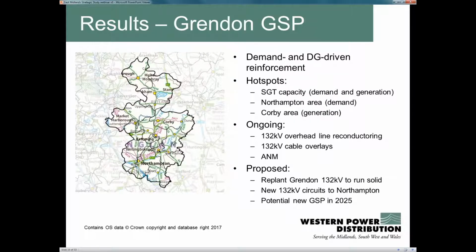Grendon GSP has both demand and generation driven reinforcement requirements. These are primarily against the SGTs for both demand and generation, and then more significantly for Northampton as demand and Corby as generation. So in those particular areas, those are the ones which we'll be likely to be looking to upgrade in order to meet the future expectations of customers in those areas.